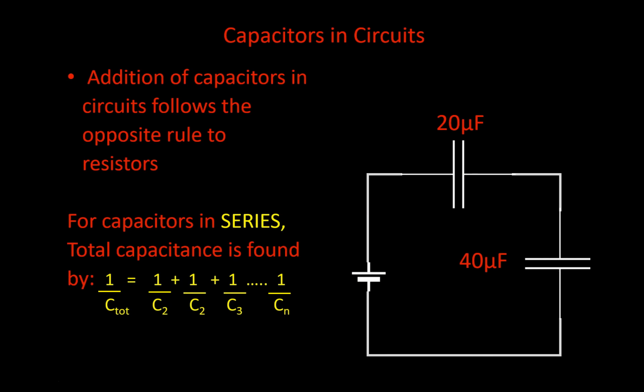Now, you're going to see a series of different rules here, one for capacitors and then later on for resistors, and those rules are actually opposite. Now in the case of capacitors, it's inverse in series. That means this is like filling buckets, and these will fill in proportion to how much charge they can hold. That means your capacitors in series are inverse, so that 1 over the total capacitance is 1 over C1, this should say, plus 1 over C2 plus 1 over C3.